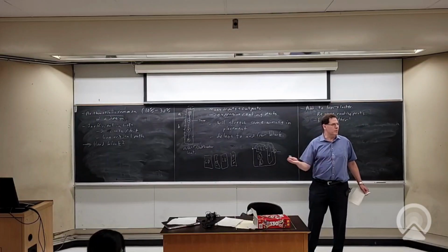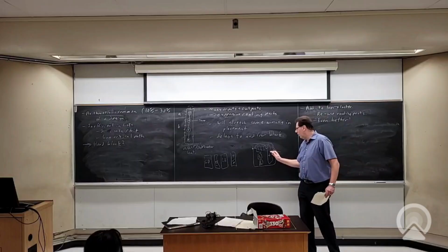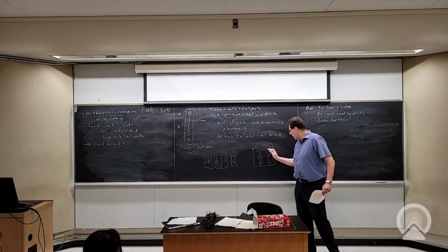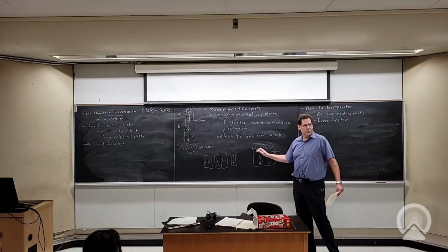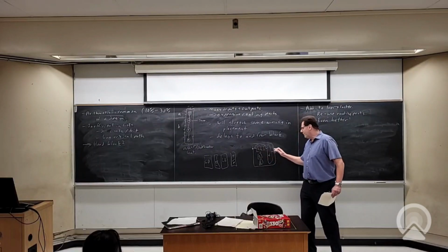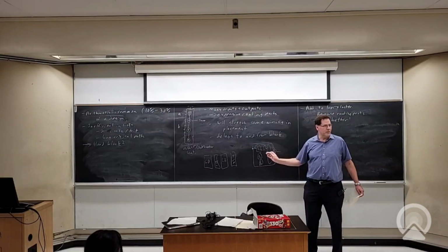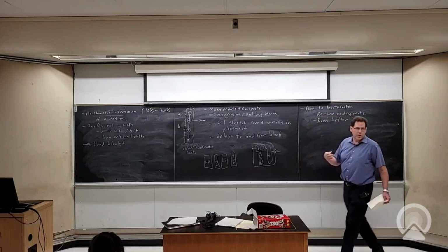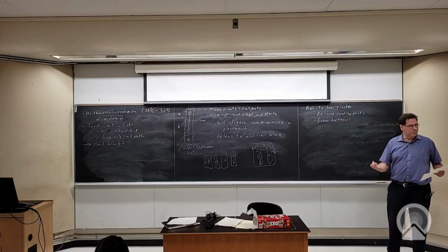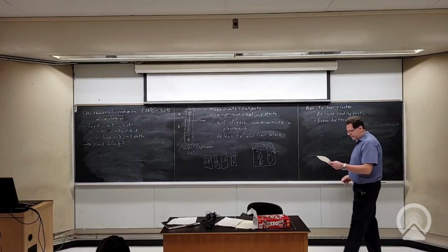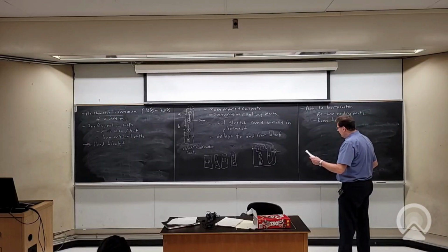So that's fine too. You don't lose any functionality, but a lot of the time, when you use the adder, you'll be able to do some LUT logic in front of it. I don't have to build more inputs. I don't have to build more outputs because I'm going to force them to be cascaded. That's effectively what hardened carry chains are doing. There's a bunch of different variations on it, but that's basically the idea.